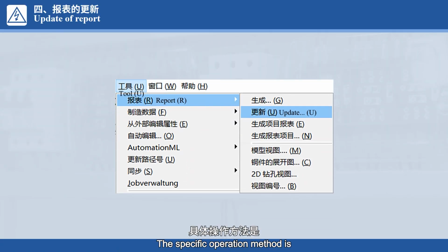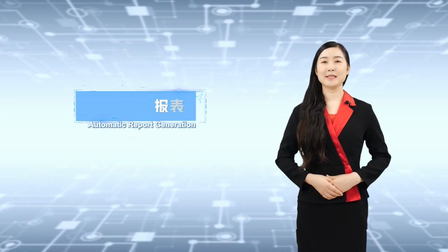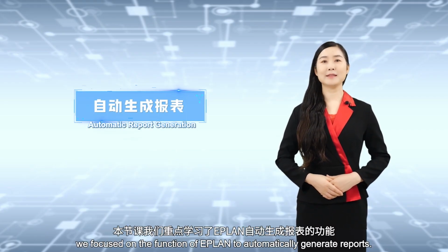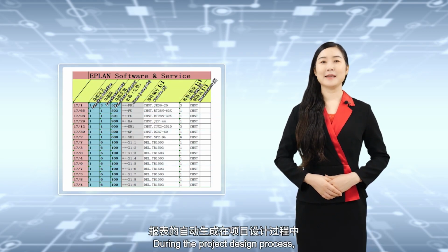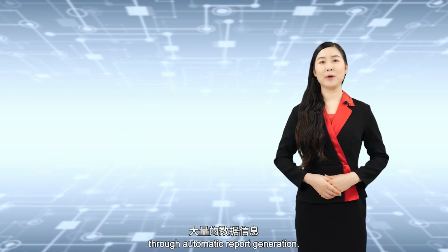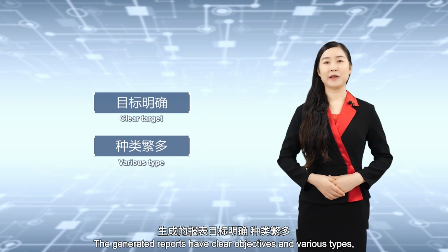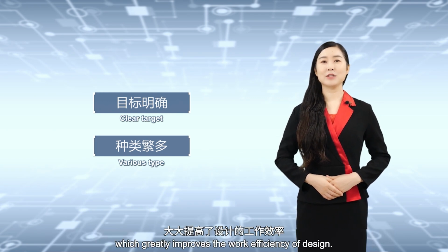The specific operation method is to select the whole project in Page Navigator and click Tools, then Report, then Update to complete report update. In this lesson, we focused on the function of E-Plan to automatically generate reports. During the project design process, a large amount of data information is screened and summarized through automatic report generation. The generated reports have clear objectives and various types, which greatly improves the work efficiency of design.